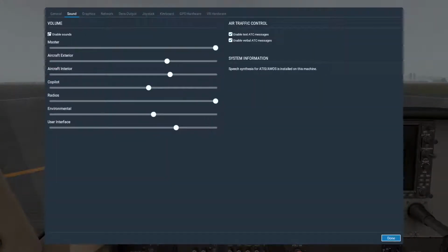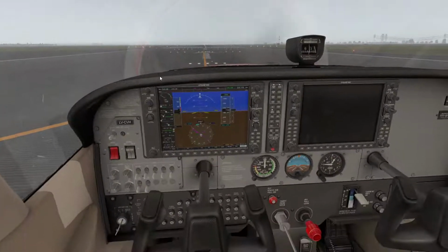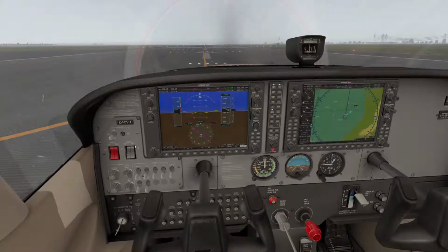Our top altitude, we don't have any ATC, so we're going to set this to flight level 330 right off the bat. Everything looks good. And we are just about getting ready to go. So I'm going to go ahead and close up the flight engineer panel here. Let's get our fuel pumps on. Hydraulics A, and B.